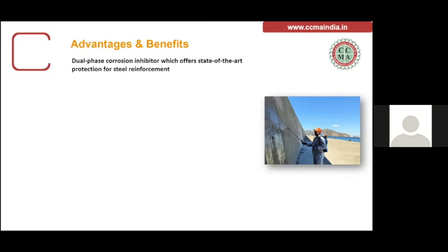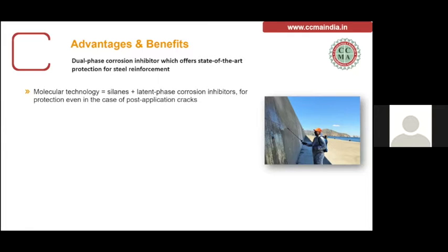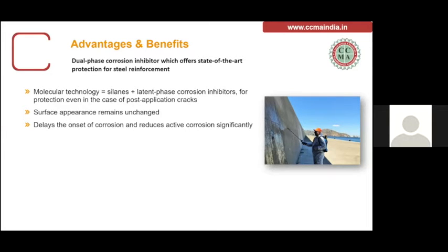So quickly going through a few of the advantages and the benefits of this. As I said earlier, it's a nanotechnology system, and the silanes and the latent phase corrosion inhibitors are more important even for post-application cracks that may happen. The surface appearance remains unchanged if you want a firm finish concrete. It delays the onset of corrosion, and is effective against both chloride as well as carbonation induced corrosion.